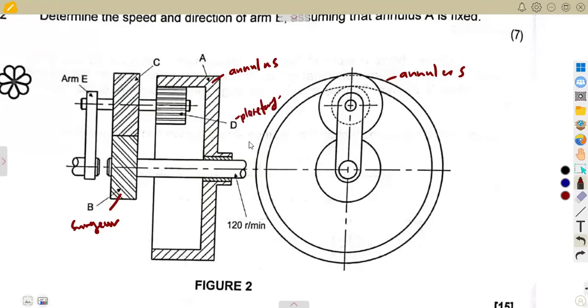This is the major part that we are supposed to think of. And also we have got gear C, which is an inline gear, which is at gear D, meaning these are at the same speed. So guys, you see the way I'm doing now, an inline gear, which is at the same speed as D, which is our planetary in that case.